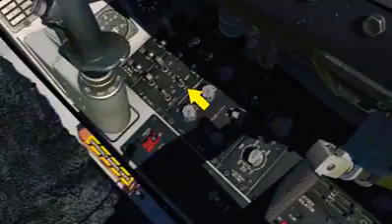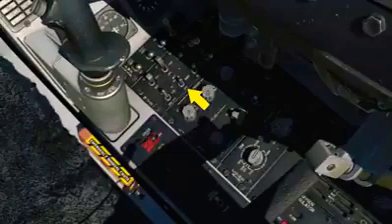The airspeed switch allows the airspeed to display as calibrated airspeed, true airspeed, or ground speed. The altimeter switch allows the altitude tape to indicate radar altitude, barometric altitude, or automatic. When set to automatic, radar altitude is displayed when the height above ground is less than 1,500 feet, and barometric altitude is shown when above. The HUD brightness switch has default settings for day and night, and an auto brightness function